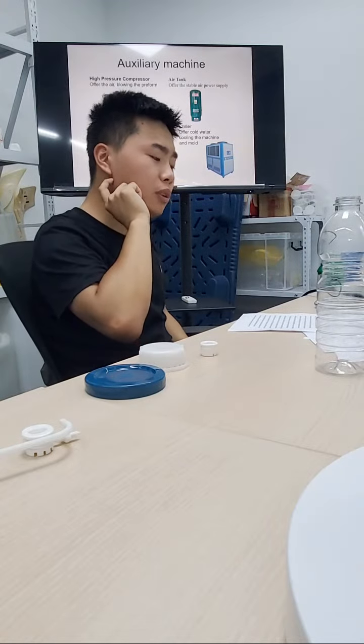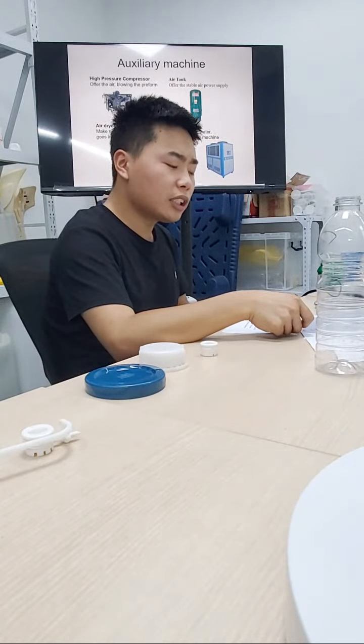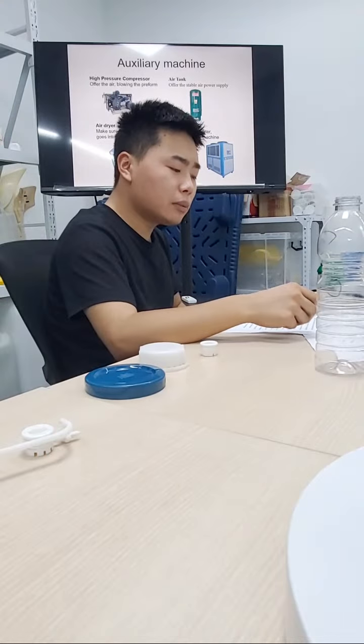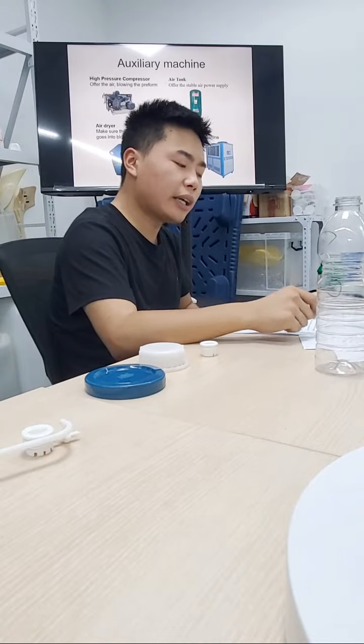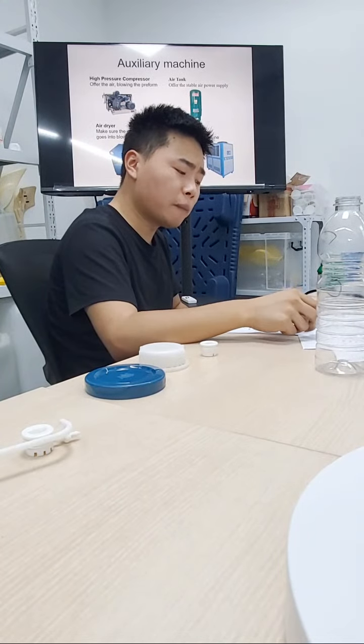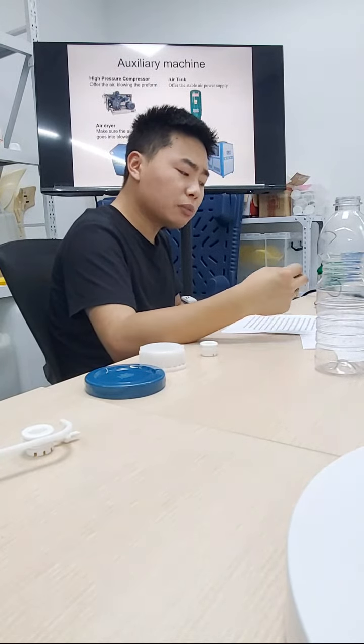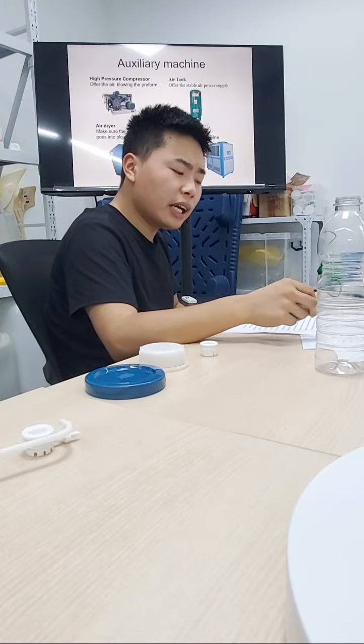And we need to know how to choose the machine. Which machine is suitable for you? Now let me tell you. The bottle size, weight, shape, output capacity, and purpose all have a big effect on the machine chosen. If the bottle is big in size and weight, we need more material to produce it, so it needs a longer cooling time. The shape of the bottle also has a big effect on the output capacity. If you want to make flat bottles, the output will go down a lot. It only has half of the normal bottle output.